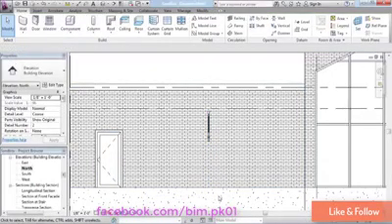So if you're not one of the three categories Revit displays automatically, and again, one more time, those are casework, windows, and generic models, then the object will not display by default. But if you just employ this simple little trick and add an invisible line cutting through the cut plane directly in the family, you can make those elements display.